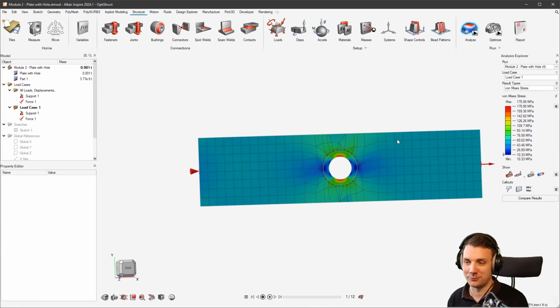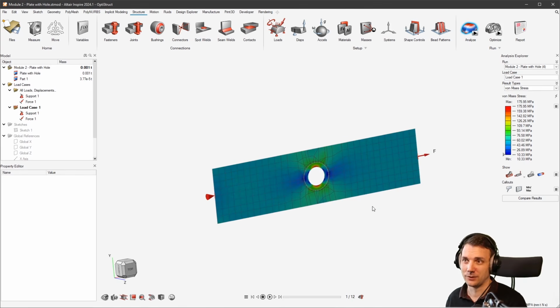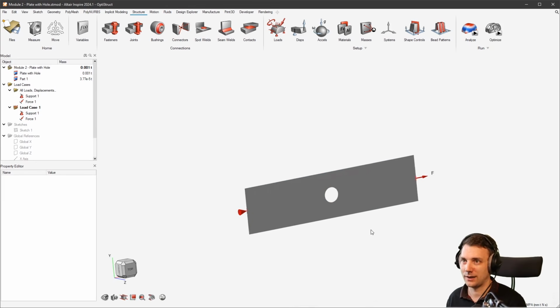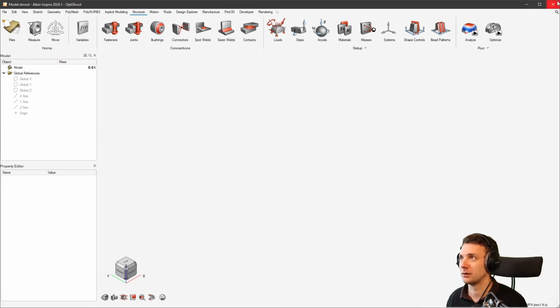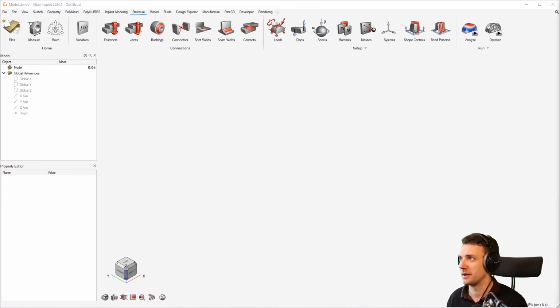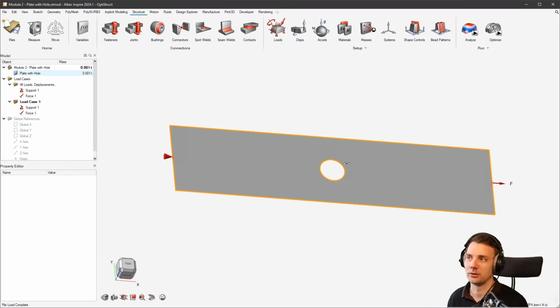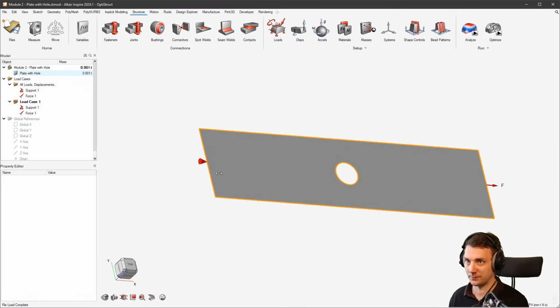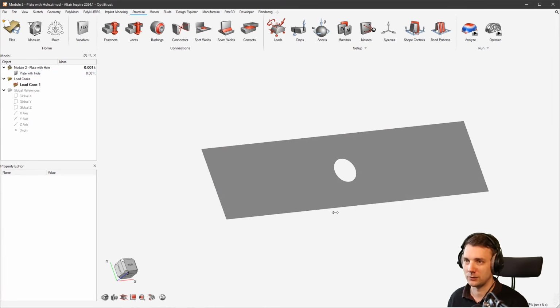But now I promised you that we would also look into the SimSolid side of things, because there you don't have anything to do with meshing, because SimSolid, the solver there, is a meshless solver. So let's check accuracy and also time here. For this, I will just go with a fresh new model and just drag the geometry back in. The boundary conditions are there too, but let's delete those boundary conditions, as we have to do an operation first.